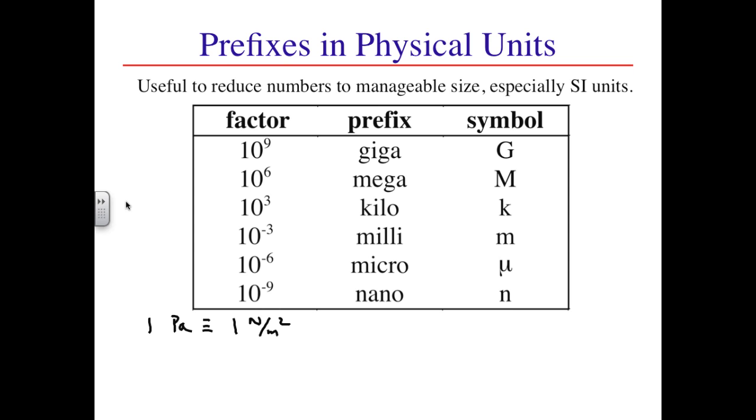to be equal to 1 Newton per meter squared. And for example, the elastic modulus of steel is 200 billion Pascal, 200 billion Newton per meter squared. So often when we're reporting these stiffnesses in SI units, we report them just as 200 GPa, 200 gigapascals, or 200 times 10 to the 9th Newton per meter squared.